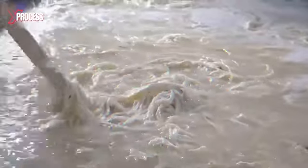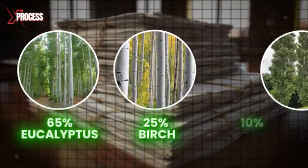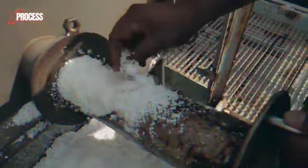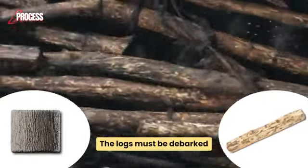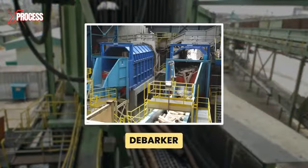Paper is made from a pulp that contains 65% eucalyptus, 25% birch, and 10% poplar. To produce 1 ton of paper pulp, 2 tons of wood are needed. First, the cellulose must be extracted, but bark is rich in tannins and other unwanted chemicals, so the logs must be debarked. This process takes place in a debarker that removes the bark from the logs.